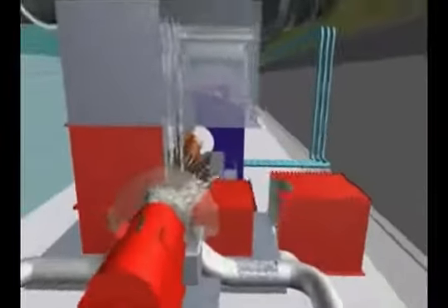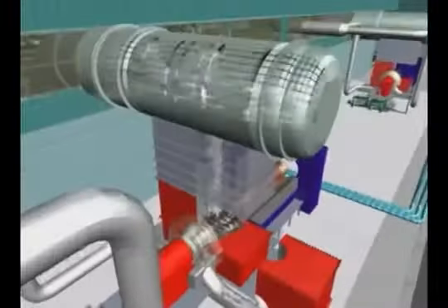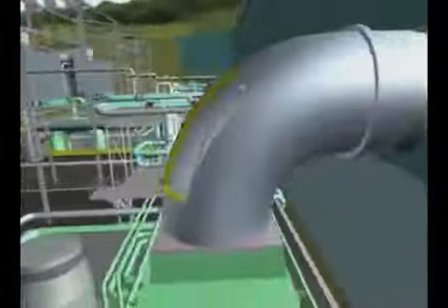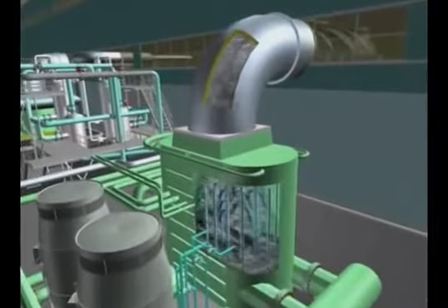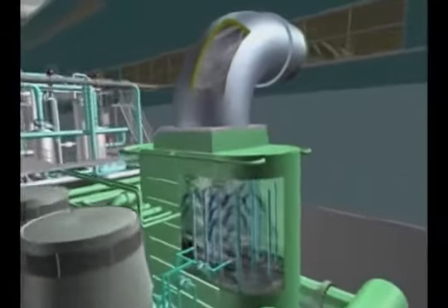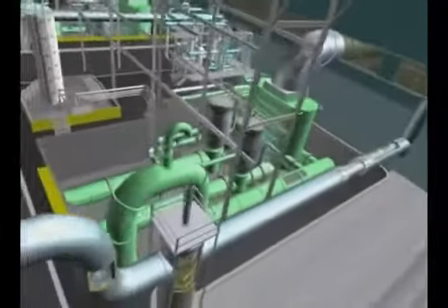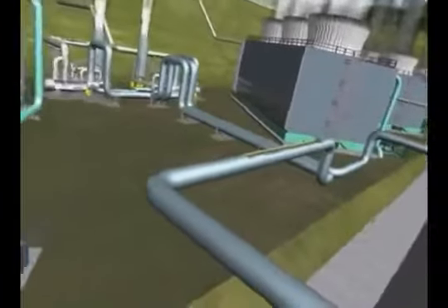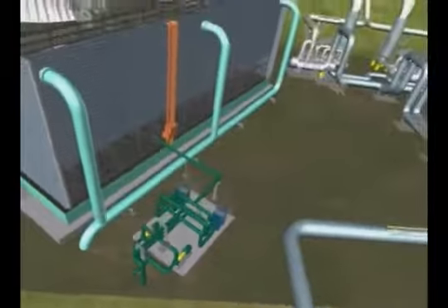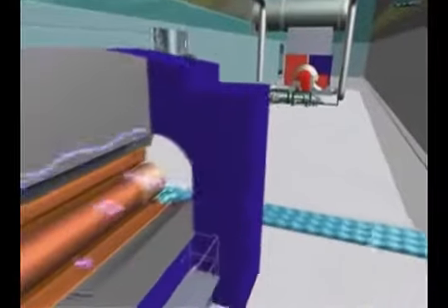The geothermal steam, after completing its function of moving the turbine, goes to a condenser, where it is converted again to water by means of internal cylinders which inject water so steam can be condensed. Once the steam is converted to water, it is pumped to the cooling towers to lower its temperature. Part of the water is used to cool some of the equipment in the power plant, and the rest is re-injected back to the subsurface.